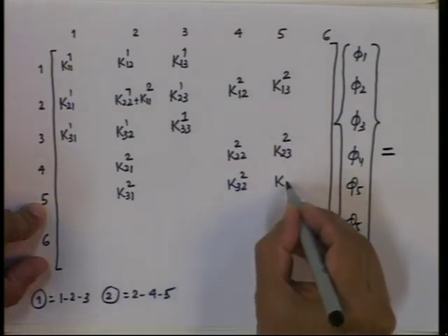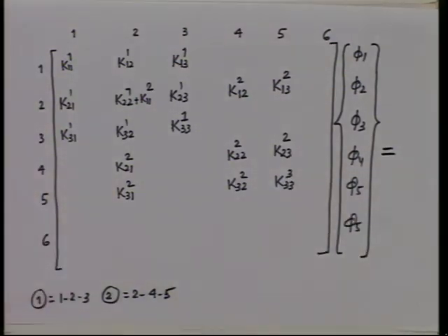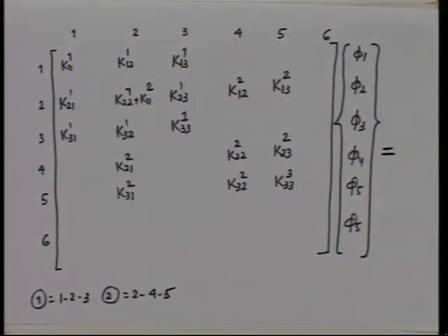See, this is called the direct stiffness method, in our structural mechanics jargon. That means, we are assembling the stiffnesses of the individual elements and putting them in the global. So, the size now is of global, but the contributions are coming from the elements, and they are put properly at the proper place.